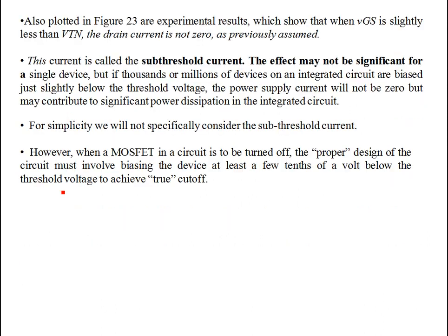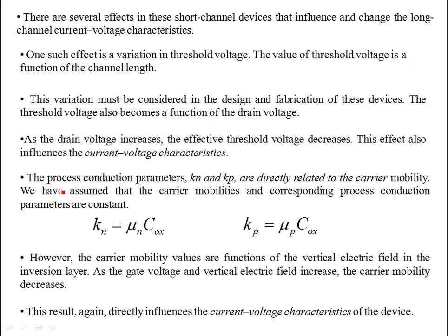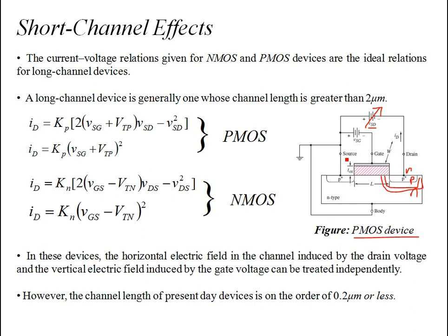So what happens in punch through is that as you increase this VSD, a point might occur where this is going to interfere with the channel. The channel geometry will be tapered off. We have discussed this before. So you're pinching off the channel, but as you go on increasing this VSD, this depletion width is going to throughout cover the channel of length L.